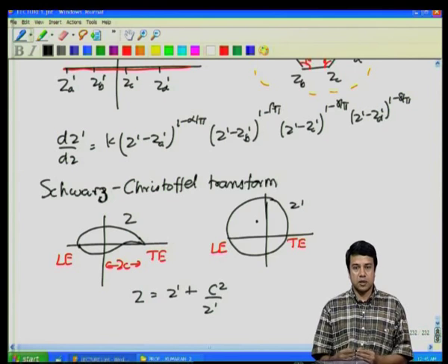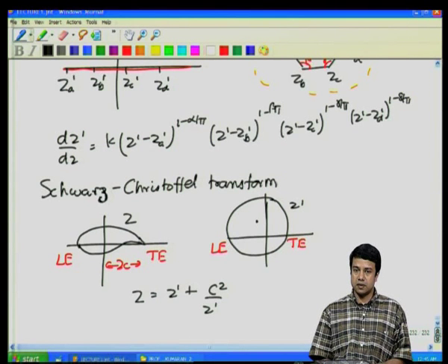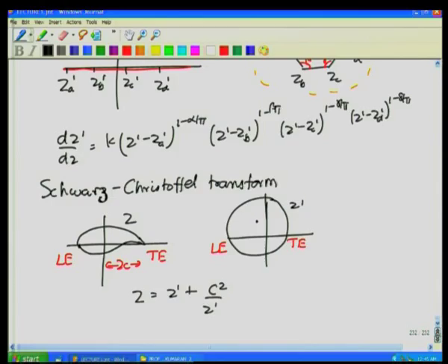Then we went on to 2-dimensional potential flows, where we used techniques from complex variables. I showed you that for any analytic complex function, the real and imaginary parts satisfy the Laplace equation. So, we identified the velocity potential as the real part without loss of generality, and the imaginary part turns out to be the stream function. Then we looked at simple flows which are generated by common simple functions. For example, power law functions generate flow in a corner, log functions generate either a point source of fluid or a line vortex in 2 dimensions.